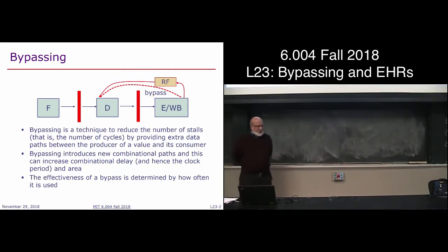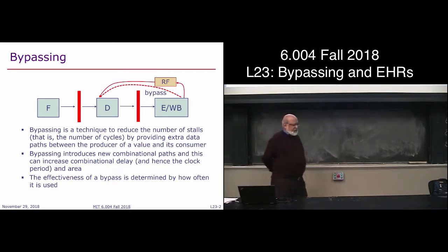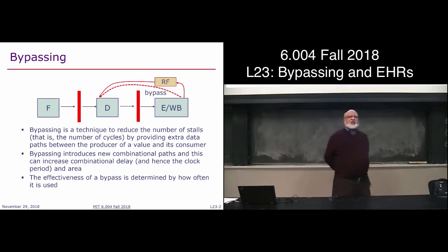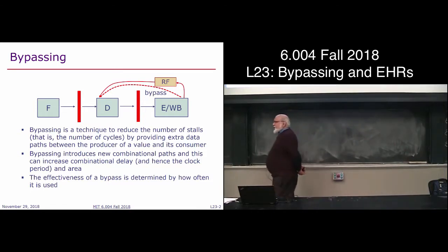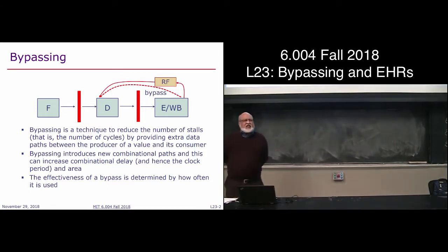The next question is that bypassing is a good idea, but there is no such thing as a free lunch, so there is some cost associated with it in terms of area, in terms of clock period perhaps. And then, should I do it or should I not do it? That depends very much on how frequently you expect the bypass to be used.